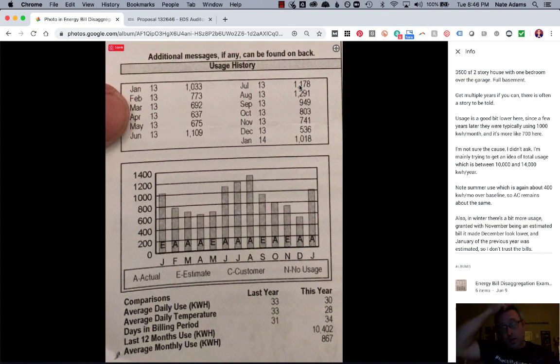So again, if you're going to promise people in climate zones 5 or 6 that they're going to save a whole lot of money in their cooling, you're smoking crack. There isn't anything to shoot at. Most of these houses are spending $200 a year on cooling. It just isn't there. So don't promise that. And frankly, it doesn't justify anything beyond a SEER 13.